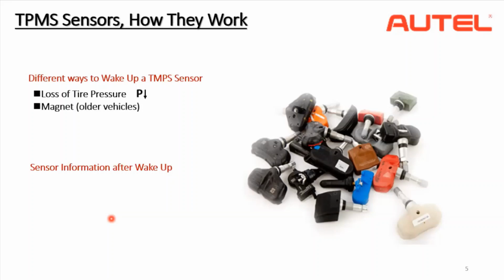And the other one is using a Relearn magnet, the activation Relearn magnet. The people who already own an Autel TPMS tool will have noticed that an activation magnet is placed on the TPMS toolbox. So basically, you could use this activation Relearn magnet to wake up or activate the TPMS sensor, and this can only be used in some older vehicles, like old Ford vehicles that need this Relearn activation tool.